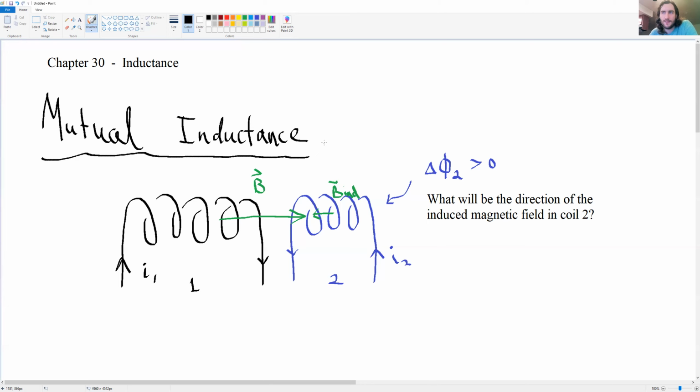What we'll see is an LR circuit, which is a circuit with a resistor and an inductor, and an inductor is basically just a coil of wire. We'll solve for a time-dependent current, just like we did for the RLC circuit, a similar type of thing. So we want to get rid of the magnetic field and magnetic flux in our formulas and rewrite them in terms of current. It makes circuit analysis a lot easier for us. So let's go ahead and do that now.